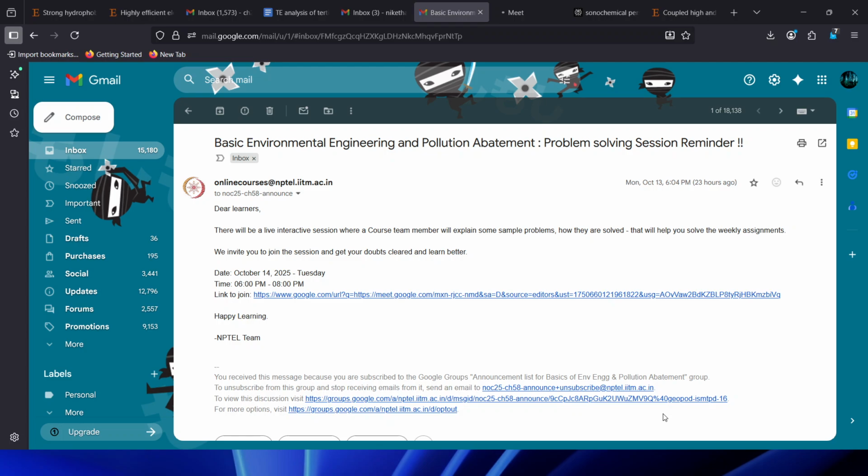Can you differentiate between a cyclone separator and a gravitational settler? Gravitational settling works on the principle of gravitational force, while cyclone separators work on the principle of centrifugal force. Can you explain how this happens in gravitational settling? How are pollutants removed in a gravitational settler?